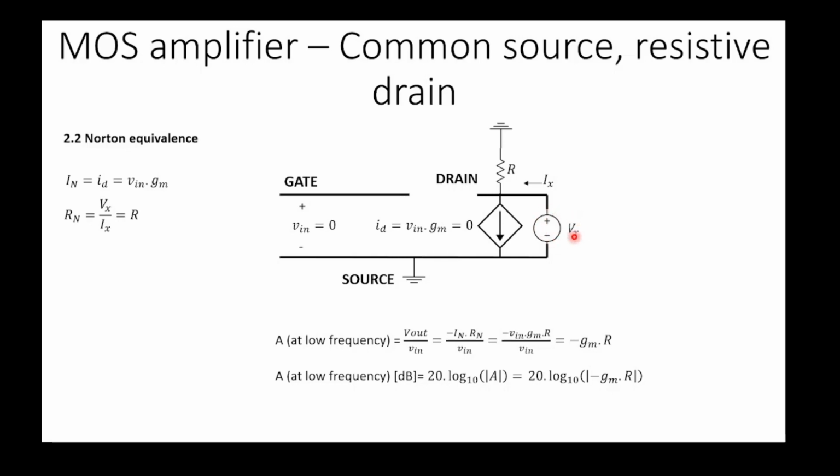When we put a voltage source Vx at the output, we have a current Ix going into our circuit, and all the sources inside our circuit need to be zero. It's somewhat similar to how we solve a circuit with many sources using superposition, if the circuit is a linear circuit.